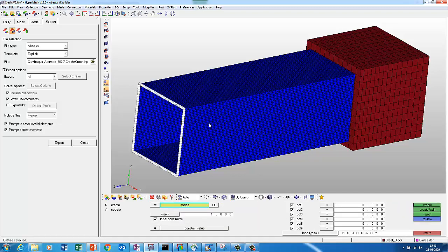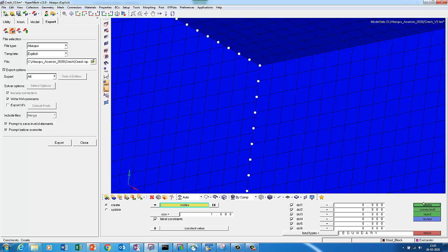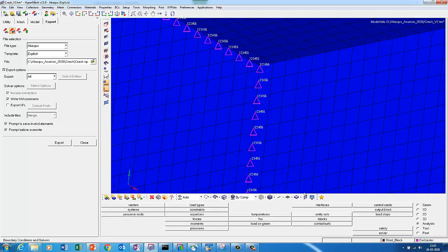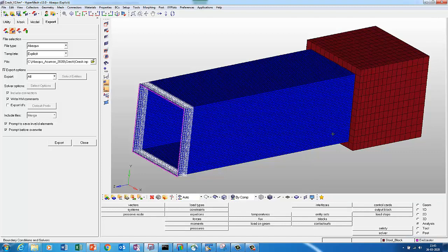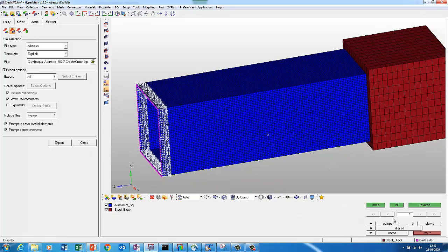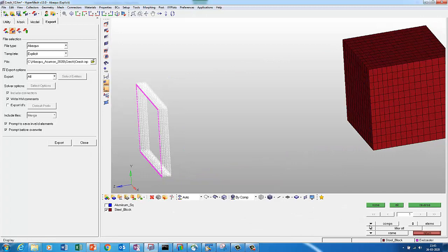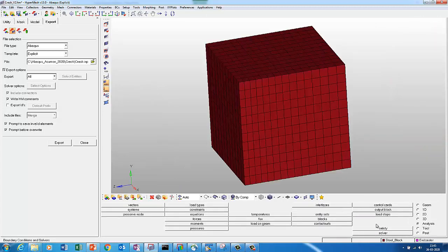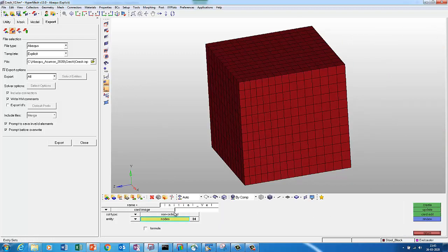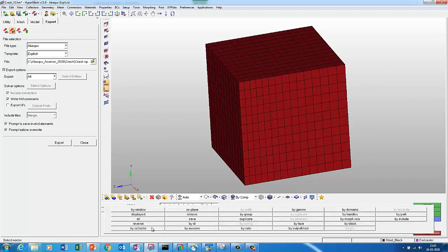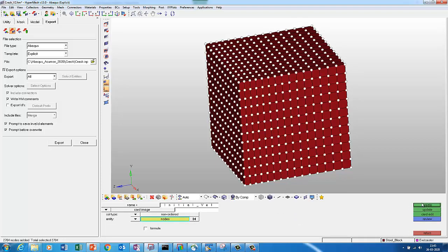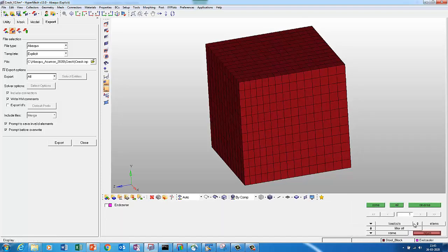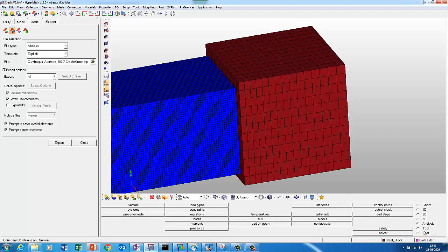So I selected node on plane and I say create. So this created the end caster condition, and I'll do one thing, I'll create a node set for block. So I say analysis entity set, initial velocity name I gave, and nodes by collector, I selected this and created. So I created a set of nodes, so I can assign the initial velocity to that.